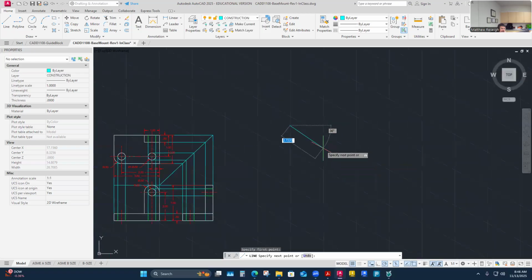So I'm looking at this as the bottom of the front view, so it's the overall width here. That is 3 inches. So I'm going to make this line 3 inches long on this 30 degree plane here, which I could tell matches the grid. My lines should be parallel with that grid, which is why that grid's helpful. It's just behind you, and keeping things parallel to that grid is what I'm doing. So this is 3 inches, right?